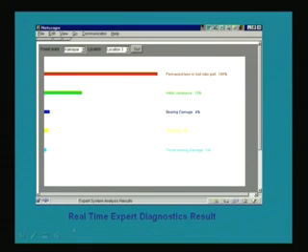This was a typical plot from an expert system. You can see that based on the recent data captured from the machinery, the expert system is predicting the probability of various kinds of faults in the machinery, and you can see that the maximum probability it has assigned to the permanent bow or loss of rotor part in a particular machine, and others are having less probability.